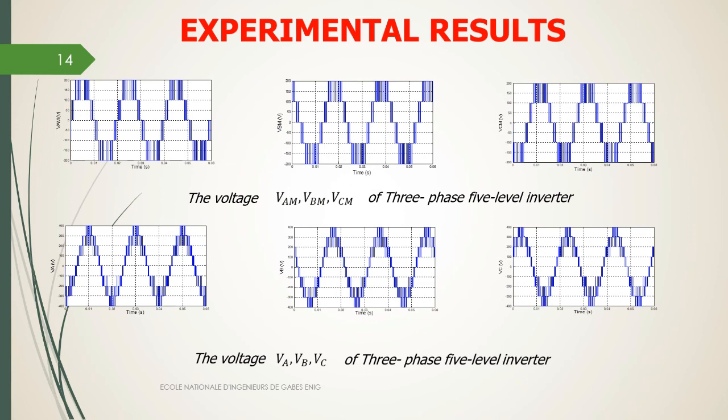The purpose of this work is to give the modulation and simulation of the NPC inverter of 5 levels with sinusoidal SPWM control, and to give the compound voltage and the single voltage of the network. And finally, we conclude with a small conclusion.